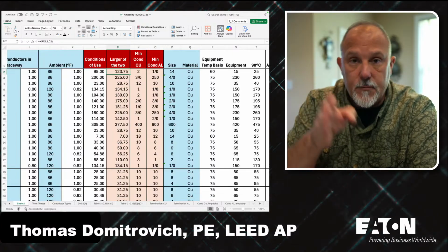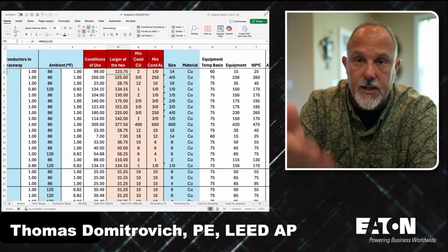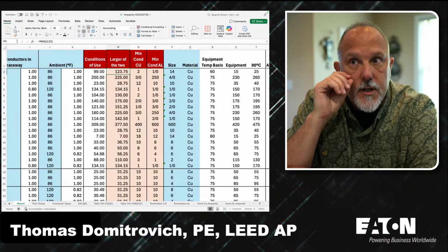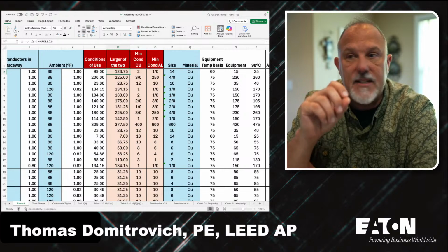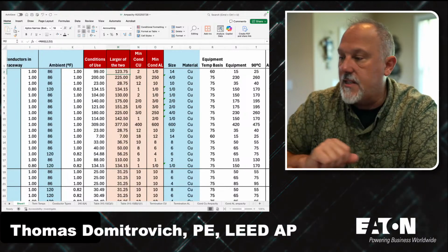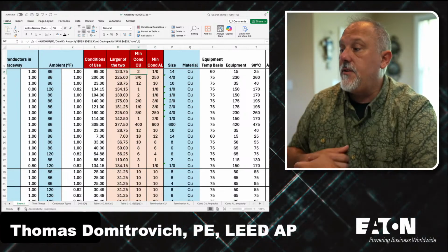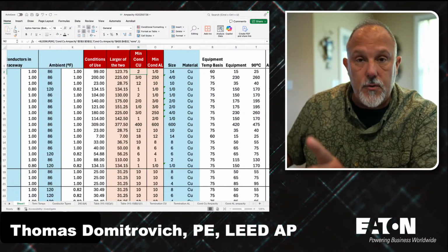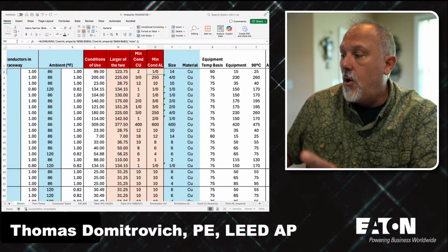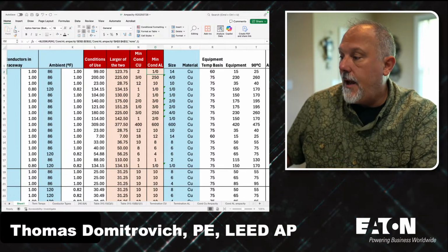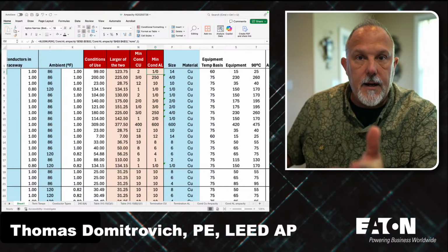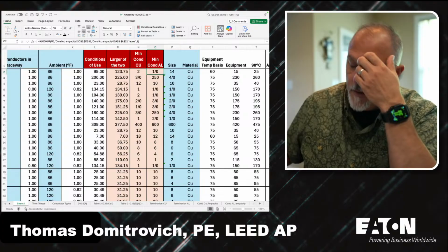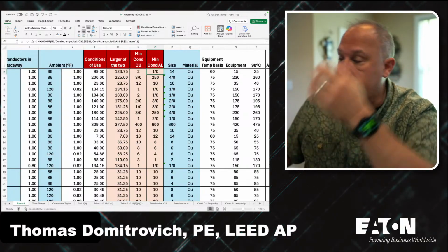for feeders and branch circuits, or branch circuits and feeders, Article 210 and 215. The minimum conductor size has to have an ampacity of at least 123.75. And then I do the calculation. I go into the conductor. So that would be a minimum size of a 2 gauge copper or a 1/0 aluminum. And that's based upon the 90 C column of those conductors in 310.16.